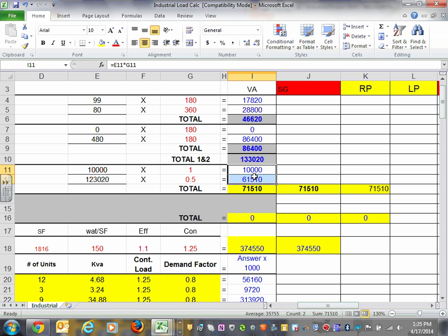Can you guys see this scale here? Does that make sense? I'm not an accountant, but right in here, you add them up. So your allocated demand receptacle load, I call it receptacle load, right now is almost 72 kVA. Can you guys see that? 72. So that's where you size your receptacle panel. They're going to size from your transformer for that panel, and you're going to size your feeder, and a bunch of other things.